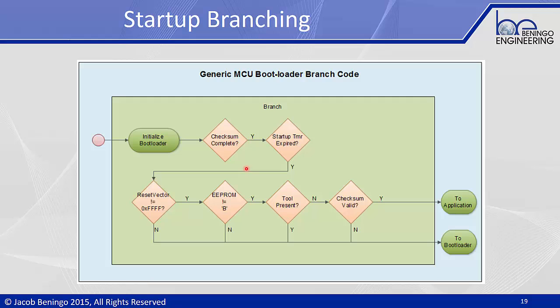And what we can do then is perform these checks. So here's an example of what these checks might look like. I turn my system on, the bootloader starts up, it initializes the system. I'm in a good controlled and known state. One of the things I'm going to do first is start performing an image checksum in the background. I want to verify that if I sum up the application space, it matches a checksum that's programmed at the time that the application was. It's possible that the application code could have somehow become corrupted, and I just want to validate that the system integrity is intact. And that is going to take some time.